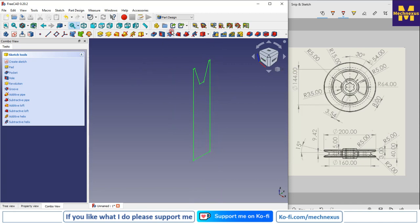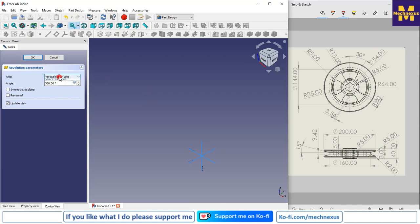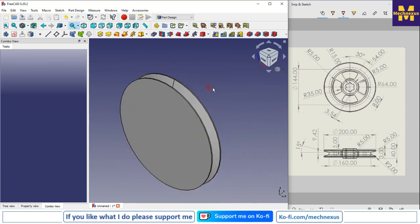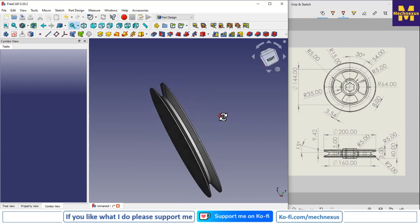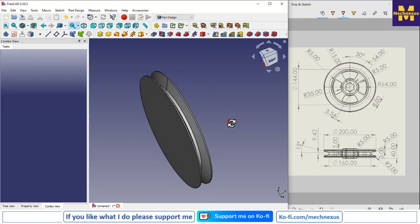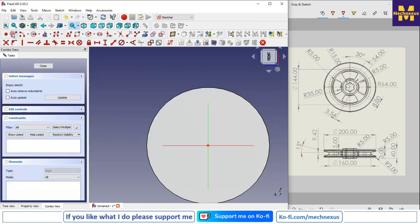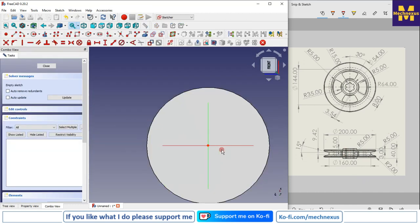Now we will use the revolve feature. So here is a revolution, and from here I will select reference. So I will select this one and I will say OK. So this is the base profile which we have created, and now we will add these two bosses. So I will select the face and create a sketch, and we will see the diameter.